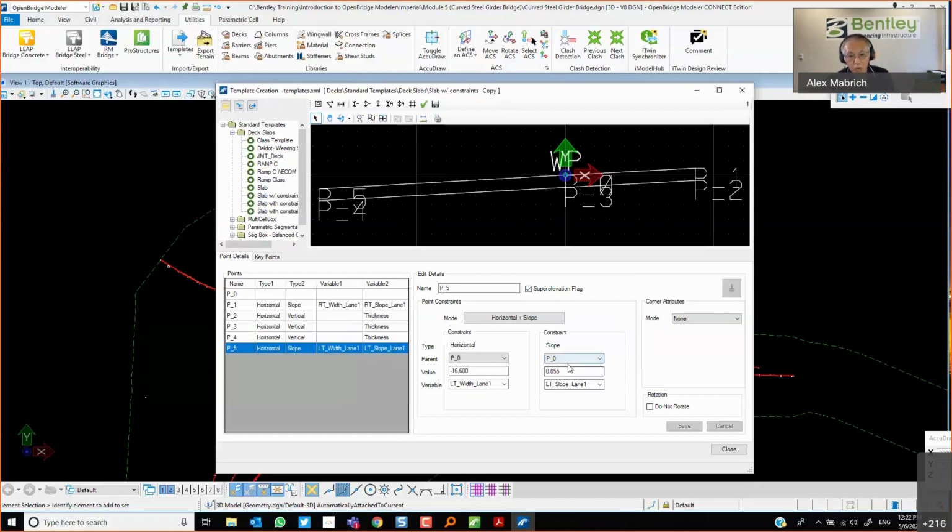So here I'm hard coding the super 5.5%, right? But then if they give me the super elevation file and I want to override that, I just attach it, apply it, and it will overwrite. Because of this, it will overwrite whatever number you set up.